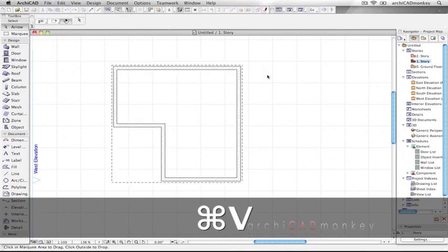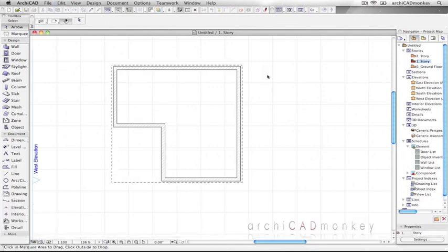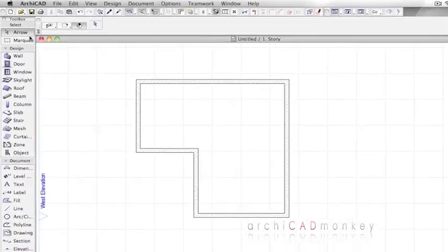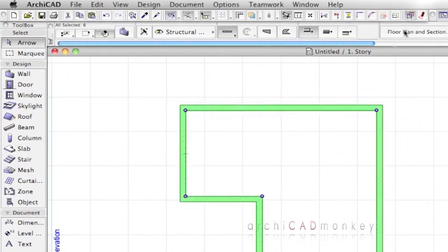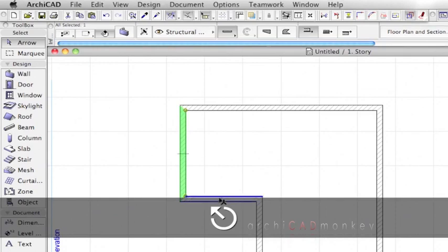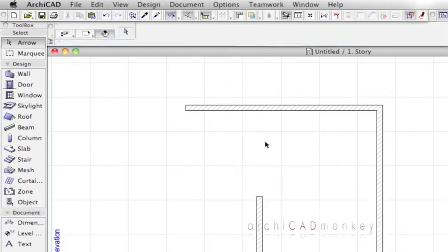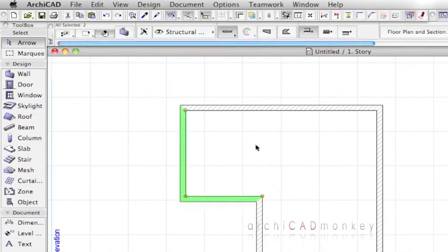Now you'll see the four walls appear with a marching ants outline as it's commonly referred to. Click anywhere outside the outline to complete the action. Go to the arrow button at the top of the toolbox. Select the two walls on the left. Whoops, let's suspend the groups again. Escape, and now select them again. Press the backspace button to delete them, or right-click and select Delete.